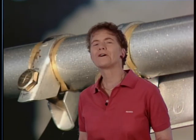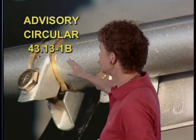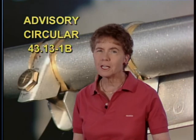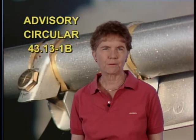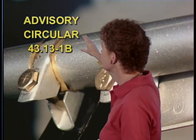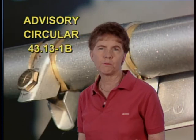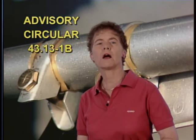Now, when you're installing nuts and bolts, where do you look to find the standards for how much the bolt, studs, and screws should protrude through self-locking nuts? Well, you'll find it in Advisory Circular 43.13-1B, Acceptable Methods, Techniques, and Practices for Aircraft Inspection and Repair. You need to know the number of that advisory circular well, because you'll refer to it often in your career. Now, do not confuse this advisory circular, 43.13-1B, with another similar sounding one, 43.13-2A. That advisory circular, -2A, tells you about aircraft alterations.